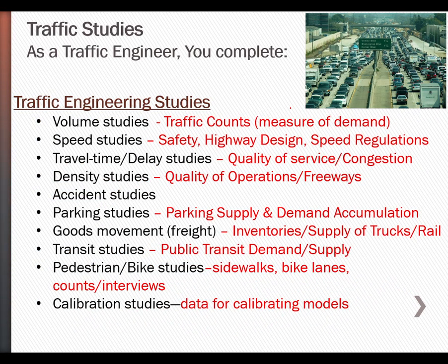Okay, talking about data, let's talk about the different studies you'll probably be doing if you work as traffic engineers. These are the different studies and different types of data. I'm going to go very fast here. We can do volume studies, and this mainly depends on counts. Here you can see this road, and you want to know what's going on in the peak hour. Do we need to add a lane? First of all, we need to know how many cars are passing by every single peak hour.